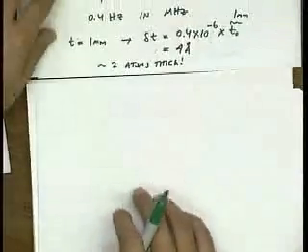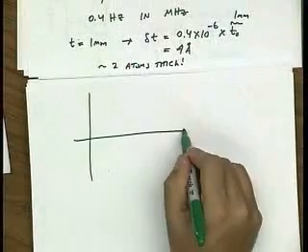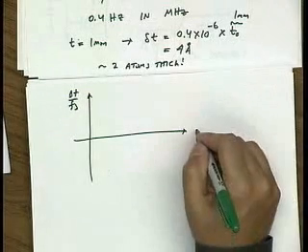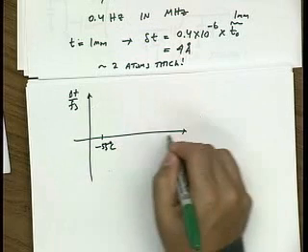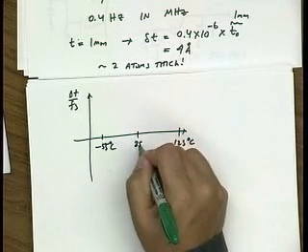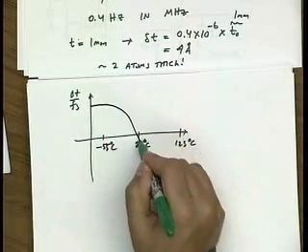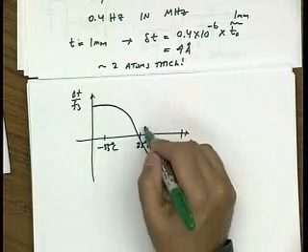If you look at the frequency stability, delta F over Fs, over, let's say, a standard range, minus 55 degrees C to 125 degrees C, you'll find that people have engineered things, obviously, to work at room temperature. So this curve goes through a nice zero right around room temperature.